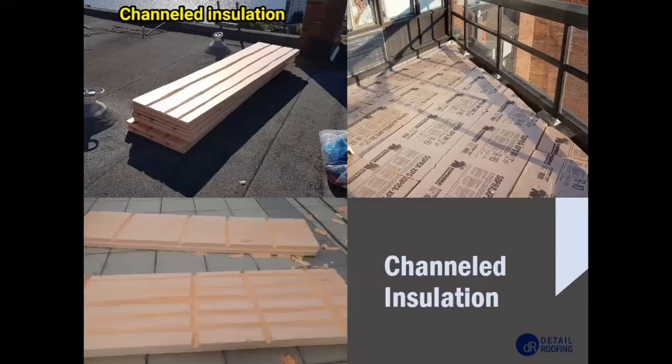So whether it is on a larger roof surface or a smaller balcony that does have an inverted system, one of the options here to encourage adequate drainage would be channeled insulation. That would just be the regular roofing insulation, but with channels cut within it. It can either be cut into the existing insulation, or there's specific channeled insulation that can be purchased from various suppliers. And again, the idea here is just to encourage the water to travel through a clearer path beneath the inverted roof system when there is a heavy accumulation of rain.